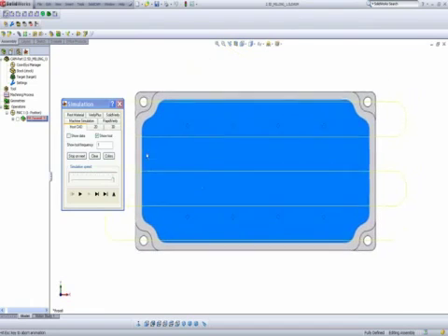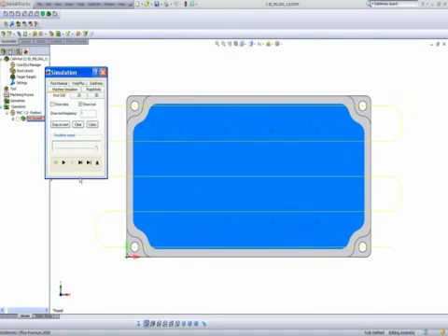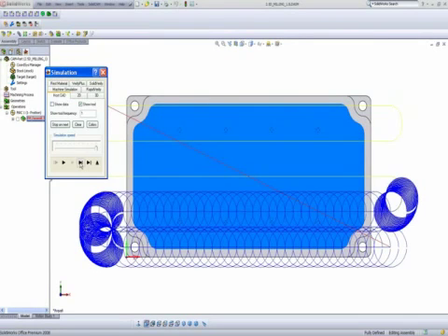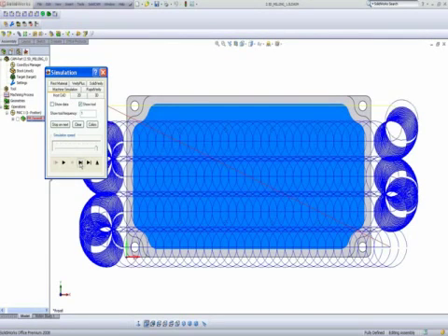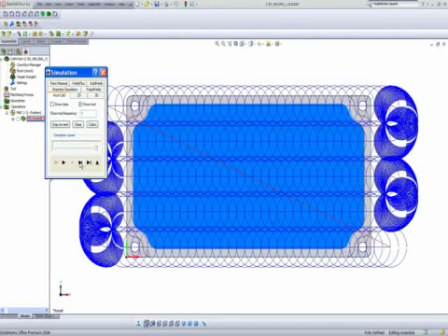Let's take a top view of the simulation in this particular case, and you'll see I'll do it one step at a time. The tool goes down, around, and as you note, it's past 25% of the tool part itself on the sides. There's a 5% overlap between the tool paths, and the tool leaves the part itself, because I wrote down 110%. If I would have done 50%, then the center of the tool would have gone over here only.